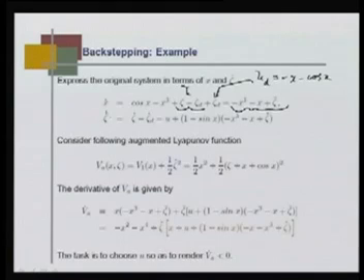and xi tilde dot, because xi tilde is a new state variable, I have to write down an expression for it, which is xi dot minus xi desired dot. Xi dot we already know is u from the original expression, and xi d dot, if I differentiate this, becomes minus x dot minus cos x into x dot.